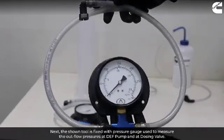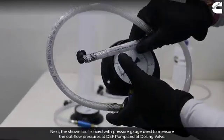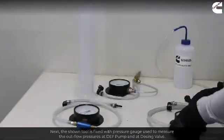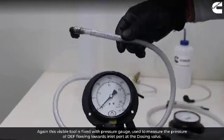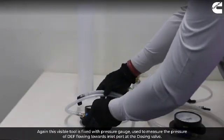Next, the shown tool is fitted with a pressure gauge, used to measure the outflow pressures at the DEF pump and at the dosing valve. Again, this visible tool is fitted with a pressure gauge, used to measure the pressure of DEF flowing towards the inlet port at the dosing valve.